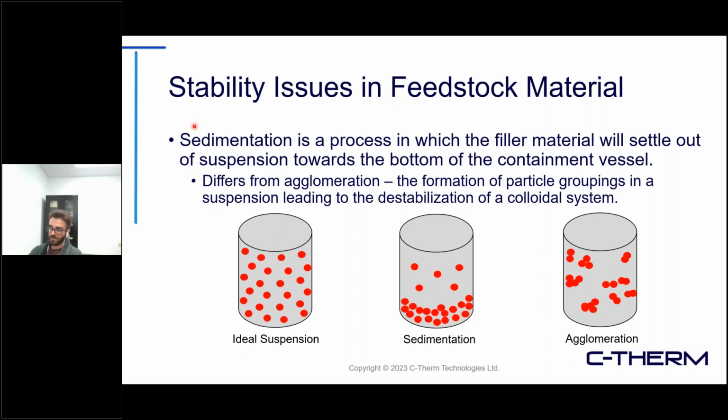Sedimentation is, I'd say, one of the bigger issues that can be at play, which is essentially where instead of having an ideal suspension, over time those fillers will eventually start to settle towards the bottom. You can also get agglomeration within the sample if they're not stable in that storage state as well. And the reason this is troubling for many of these larger groups is that imagine you have a barrel that you assume to be evenly dispersed with that filler, but it's sedimented towards the bottom.